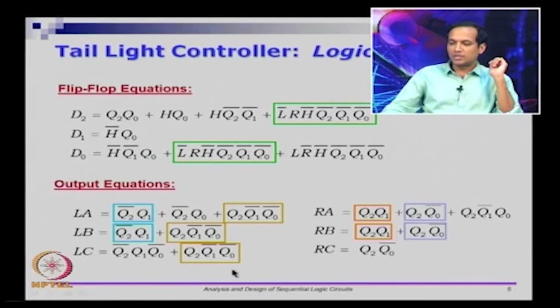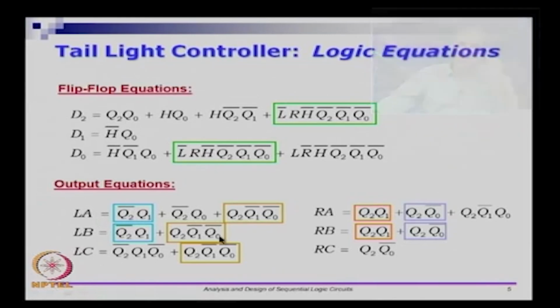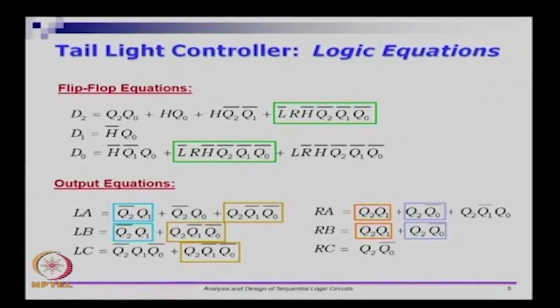Similarly, have one circuit which will do Q2, Q1 bar, Q0 bar, and use that for both LA and LC and LB and so on. So this is something you can do; you can share the gate outputs. But sometimes you wonder whether all these states are necessary or not. To do that, we are going to look at what is called state minimization.